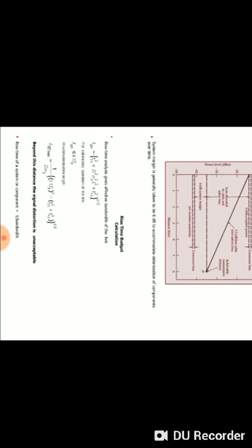In link power budget, more focus is given to power transmitted at the transmitter and power received at the receiver. Whereas in rise time budget calculation, we consider the delay present in each component in the optical communication system. So rise time analysis gives the effective bandwidth of the particular link.